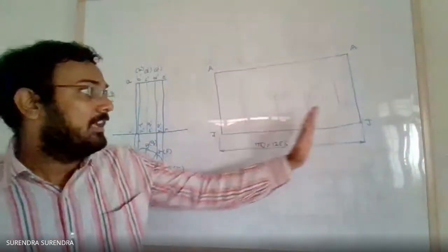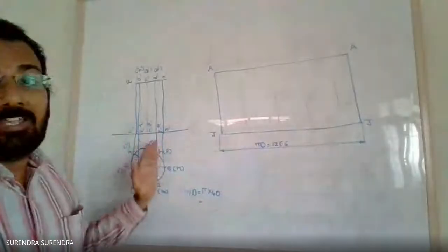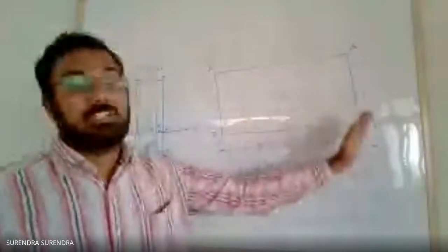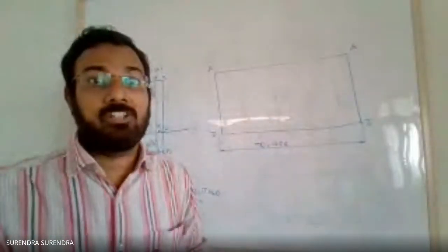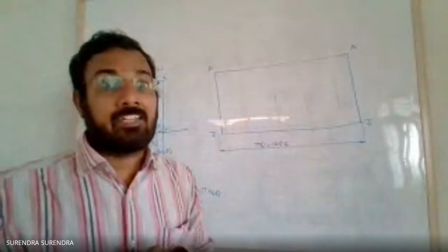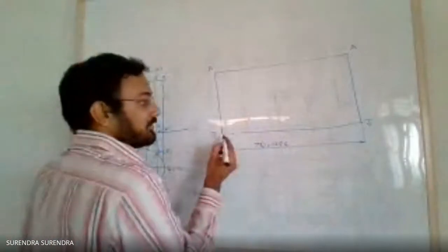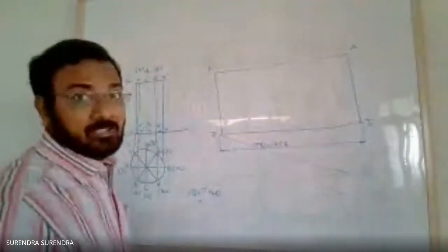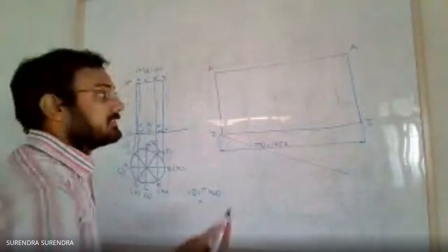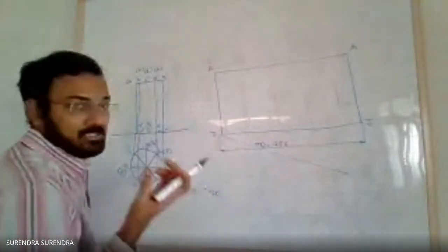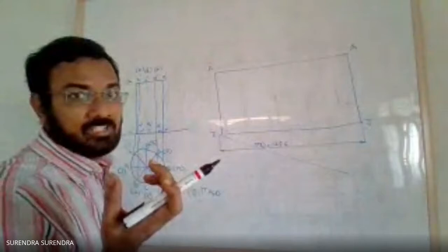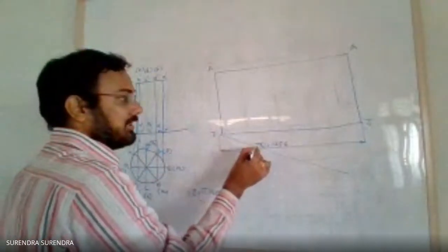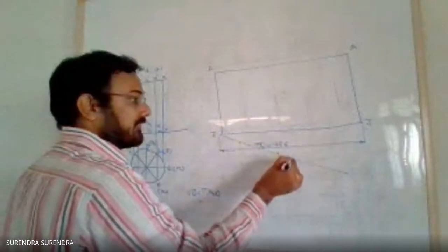Now, as we divided the circle into 8 divisions, divide the line of total circumference also into 8 parts. What is the process? Inclined line method. Draw an inclined line at some random 40 to 45 degrees, then take a compass, set a convenient radius of 1 or 2 centimeters, and mark points 1, 2, 3, 4, 5, 6, 7, 8.